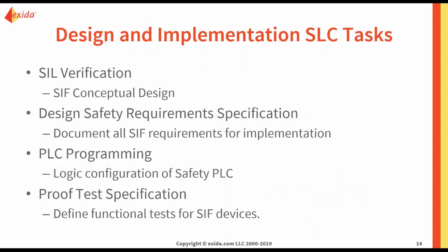If we look a little deeper, obviously in SIF conceptual design and SIL verification, you're modeling your SIF, choosing how much redundancy you need, choosing the equipment you're going to implement, and choosing your proof test strategy. Then you're going to document all the SIF requirements for implementation in your design SRS. Now that you know a lot of what you need for the logic configuration of your safety PLC, you can do that PLC programming.